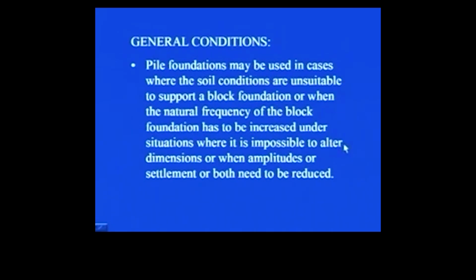You can either alter the dimension of the foundation, or you can alter the amplitude or settlement, or both. You have to reduce them to increase the natural frequency. When all these conditions are not possible and still you have to go for a higher natural frequency of the block foundation, in that case the option of pile foundation can be used.